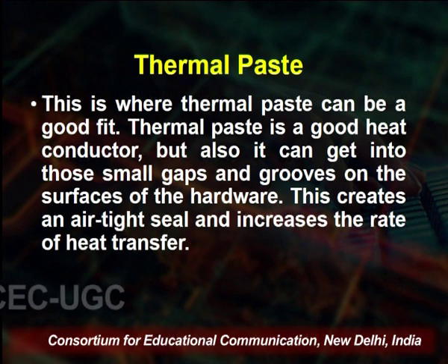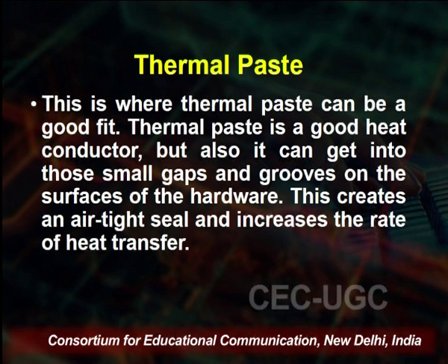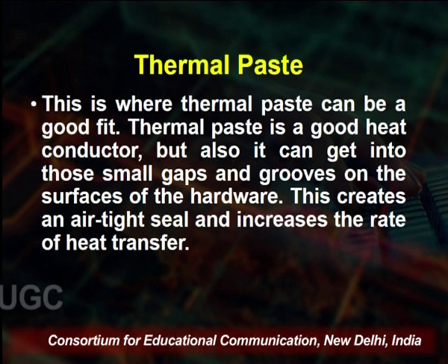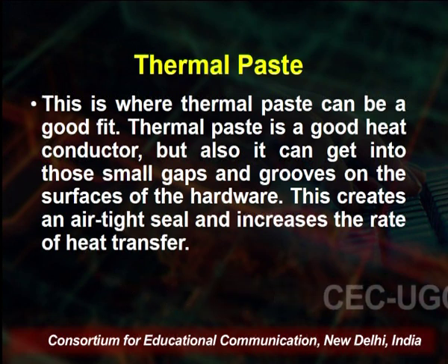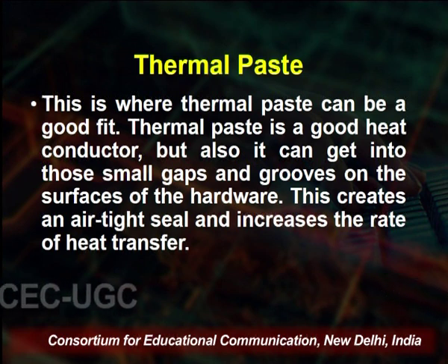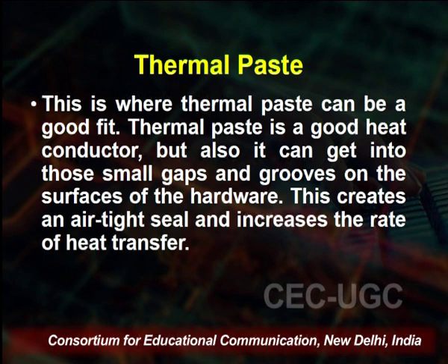This is where thermal paste is a good fit. Thermal paste is a good heat conductor, and it can also get into these small gaps and grooves on the surface of the hardware. This creates an airtight seal and increases the rate of heat transfer.